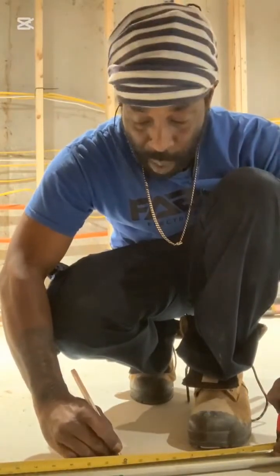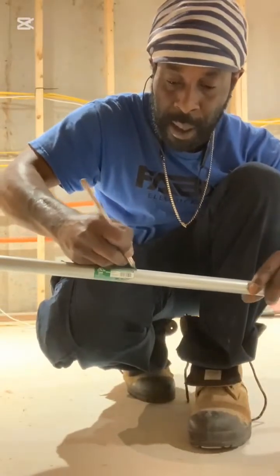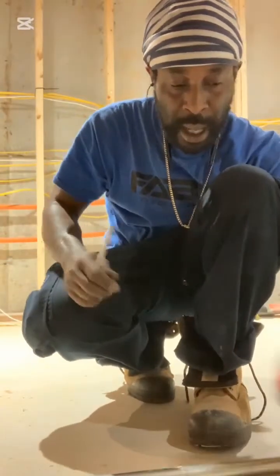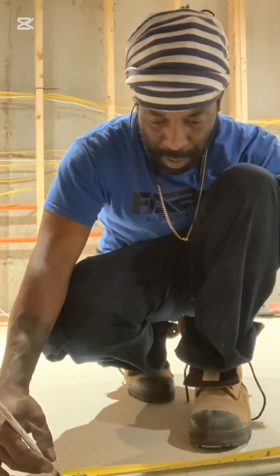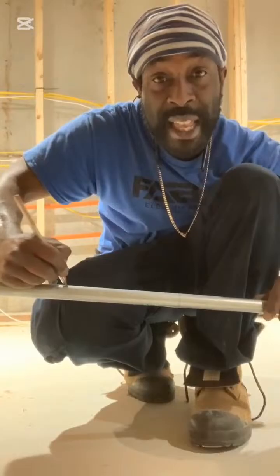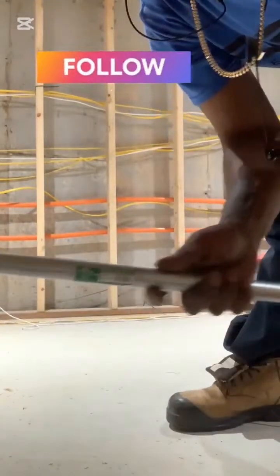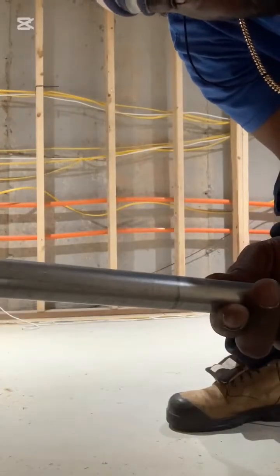So I say I want to bend at 12. Mark 12 inches. And I'm going to do the take up for 3/4. So this is going to be a 90, okay? So I have 2 marks here. One there, 1 mark here.